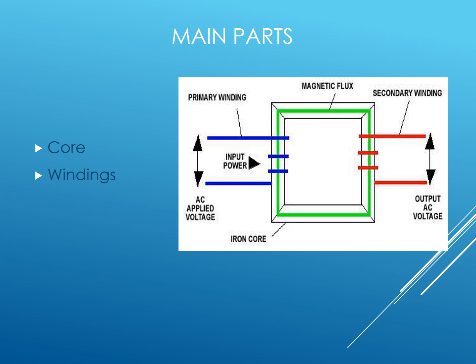If one coil is connected to a source of alternating voltage, an alternating flux is set up in the laminated core, most of which is linked with the other coil, in which it produces a mutually induced EMF according to Faraday's law of electromagnetic induction. If the second coil circuit is closed, current flows in it. So electrical energy is transferred from the first coil to the second coil.